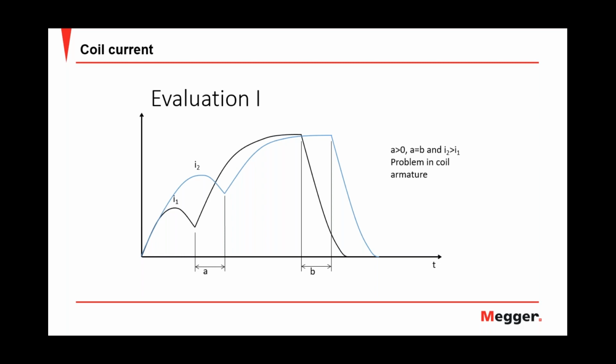And the trip coils are designed to have quite high mechanical energy needed to release the latch, but they're not designed to be continuously supplied with voltage. Usually, in normal operation, the amount of time current flows through a trip coil will be no longer than the total trip time of the circuit breaker.